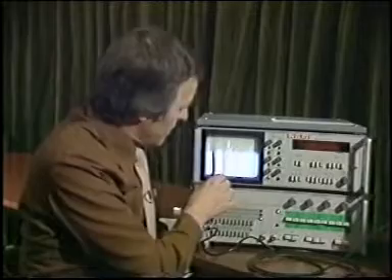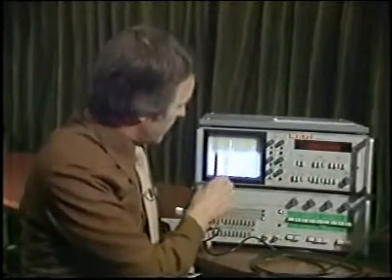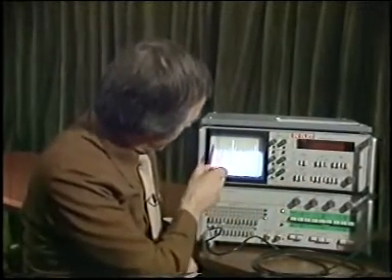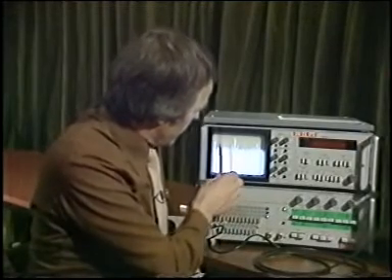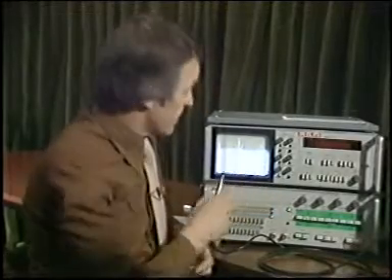Now, these are the noise that Mike was referring to. And we know, in fact, that it goes on up to much higher frequencies. This is wideband noise. And again, this is quite a high level compared with the signal. That's about 20 decibels down, but of course covers an enormously wide bandwidth, so it represents a lot more power. So, if we had a low-pass filter, hopefully we could take out a lot of these interfering signals.